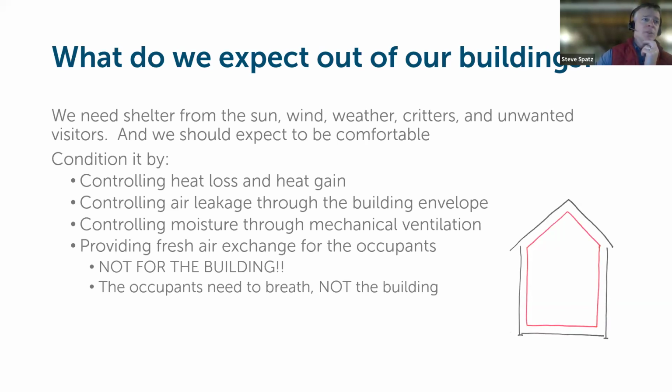The big dynamic between the 150, 200-year-old structures that we have in our built environment versus what we're building now is that those buildings were built out of material in its raw form. Those types of structures can handle a tremendous amount of moisture loading seasonally and not fall apart, because the wood is basically in its original form. It's designed to move and to manage that ebb and flow of moisture, liquid, through the material. And if you're not significantly altering that dynamic within the building assemblies, those materials will continue to do that for decades and centuries. And what we're talking about now, though, is everything I said at the beginning. We've changed that material approach, and we're not building with that material anymore.